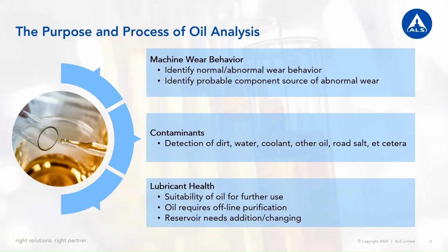All machines experience wear throughout their lifetime. However, the severity of the wear can fluctuate depending on internal and external factors. Oil analysis will allow you to see these fluctuations and pinpoint the specific component that is experiencing them. For example, if you are monitoring the elemental wear levels and see a spike in copper, lead, and/or tin, it might signify a bearing is giving out. The unit can be taken out of service and a replacement bearing installed without a catastrophic failure halting production.